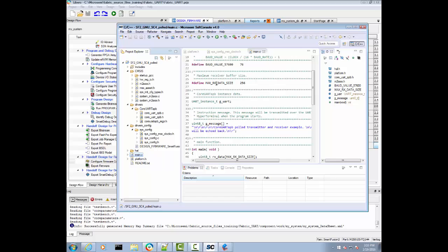The thing that's nice about that, if you run the firmware catalog from SoftConsole, when the firmware catalog generates these drivers you need, it would put them right where you need them. It would put them right in your project. I see. And those drivers, the only thing to make them functional is just update the memory map, and that's it. The memory locations, yeah.